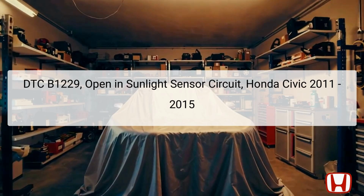This sensor is typically located on the dashboard near the windshield, ensuring it can effectively measure sunlight exposure. An issue with this circuit can lead to improper climate control function, causing discomfort. When diagnosing this error, the HDS, Honda Diagnostics System tool, is used to help troubleshoot and identify the source of the fault more efficiently. Understanding the functionality of the sunlight sensor and its wiring is essential for effective troubleshooting.